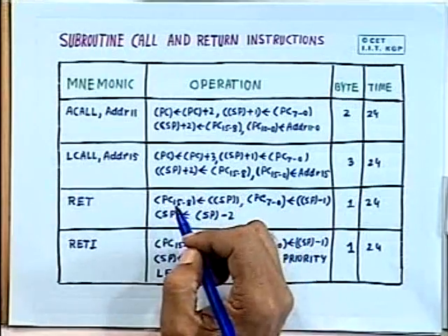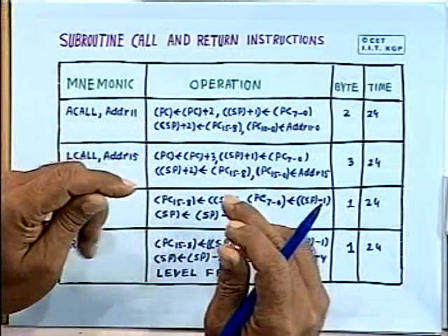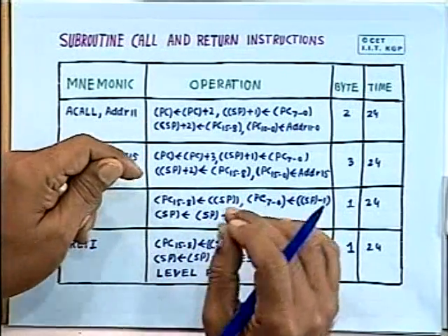The reason for that is whenever you have jumped from an interrupt, you are executing an interrupt service subroutine, there is an internal flag register known as interrupt level flag bit. You know that 8051 has two interrupt levels. So whether it is in the lower level or higher level, 0 or 1 level, that is kept track of with the help of that flag bit.